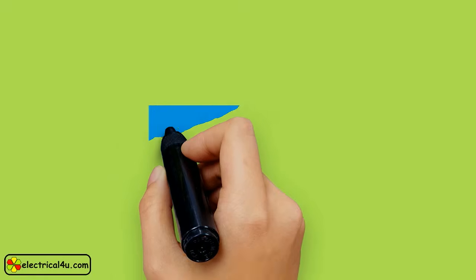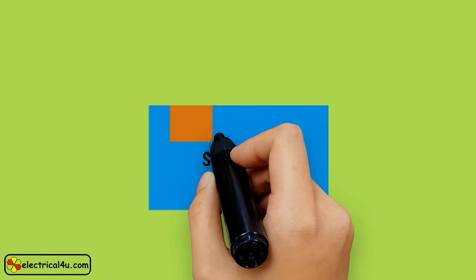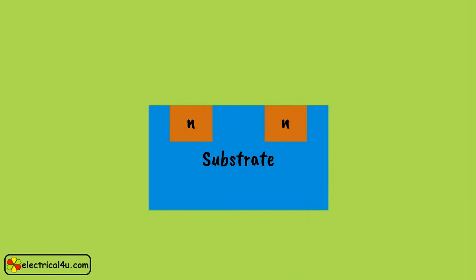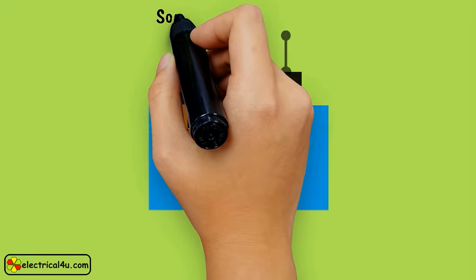Construction of the basic design of MOSFET is quite simple. Just take a block of P-type semiconductor. This block will be your base for MOSFET. We also call it the substrate, and the entire MOSFET we will fabricate on this base. Now, two portions on the same side of this P-type substrate are made highly doped with N-type impurity, as shown here in the figure. Source and drain terminals are brought out from these two N regions as shown.